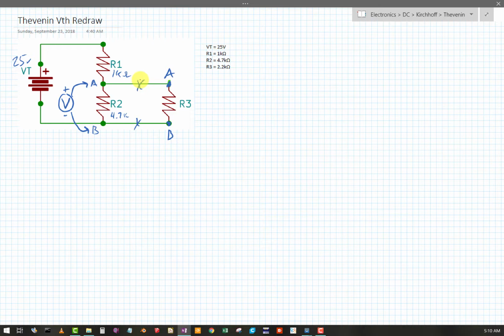Now that's all fine and dandy, but you can see my pattern recognition part of my brain has got to look at this circuit, and I've got to remove some things mentally and look for those relationships. I recommend going to a clean sheet of paper and then redraw the Vthevenin circuit with those steps applied. Now I didn't write them down, so can you remember what the steps are? Well, Vthevenin,